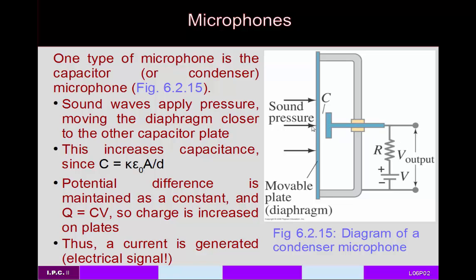Your electrical signal is the current generated from the vibration of this thing and the change of charge on the two plates. And now that you have your electrical signal, you've built a microphone. You speak in through here, that's sound waves, it's vibrating this plate that generates a signal which then is interpreted as, for example, a frequency of sound. And then how large the vibration is determines how loud the sound is. This is going to determine the maximum current and minimum current.